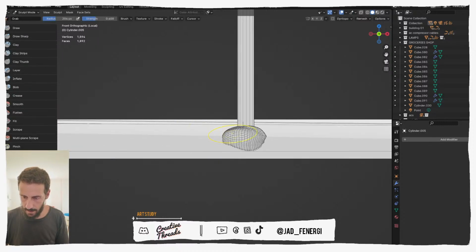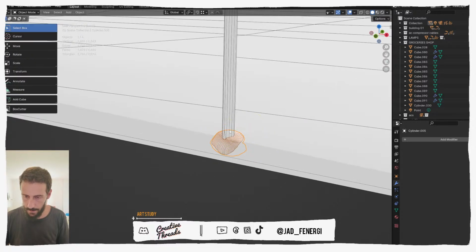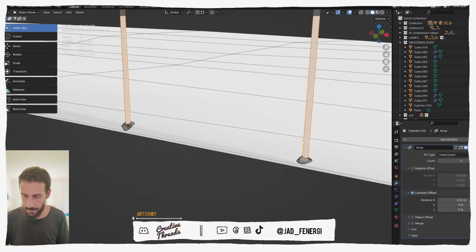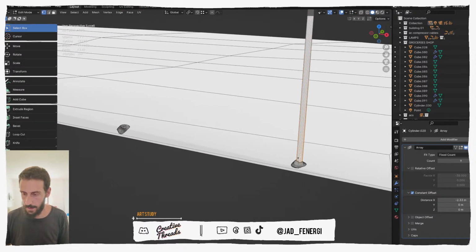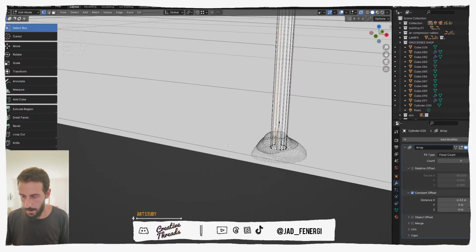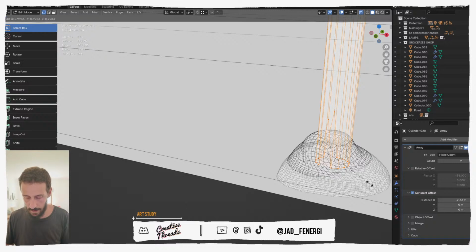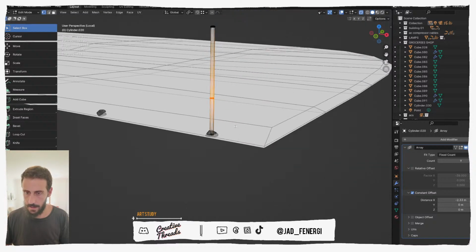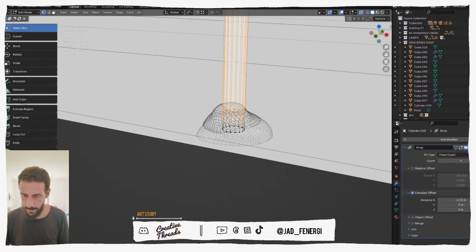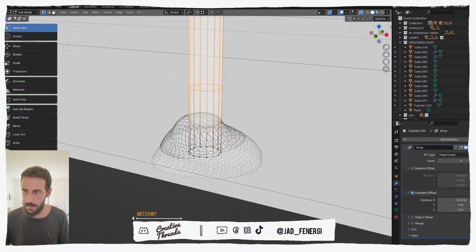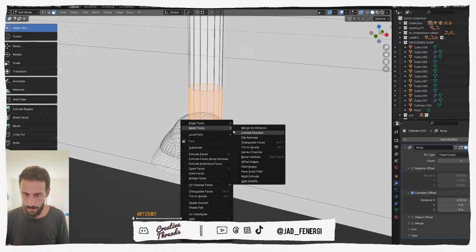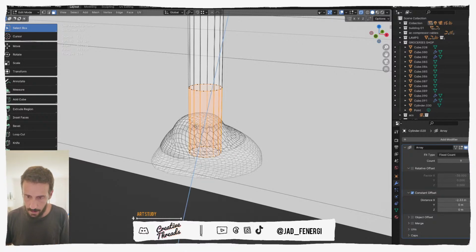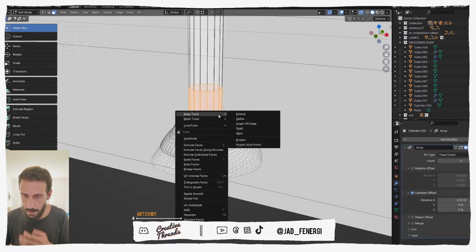Let's go to sculpt mode. There's a bit of a bulge here that I don't really like. And you know what? Let's do something here. Let's go to the edit mode. All right, these should be on the same level of scale. Push down. Let's add an edge here. Upwards a bit. Then let's pick these faces and then let's extrude. Should extrude along the normals? No, it shouldn't. So let me see.